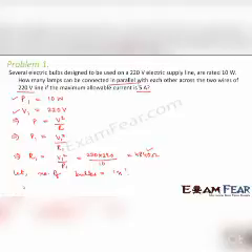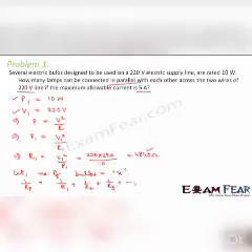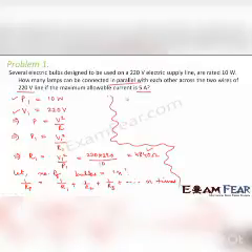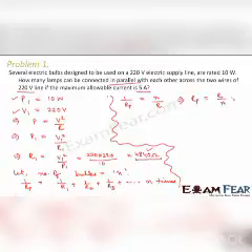So what would be the equivalent resistance of that combination? 1 by Rp, if Rp is the equivalent resistance, will be equal to 1 by R1 plus 1 by R2 plus 1 by R3. This will be added n times because I have assumed that the total number of bulbs is n. Now the values of R1, R2, R3, all these values are same, they all are 4840. So we can replace them by R. So 1 by Rp is equal to n by R. So from this we can say that Rp is equal to R by n ohms. Right? R or R1, whatever you want, you can replace it with any of these.